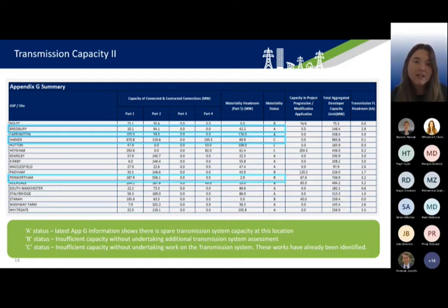Part 3 is where they're waiting to connect, but they'll have significant curtailment associated with the connection before some works are completed. So, for example, in part 3, if you've got an accepted connection for 20 megawatts, you may only be able to export, say, 2 megawatts until some works are completed. And then the works in part 4 mean that you cannot connect anything. They're waiting until those